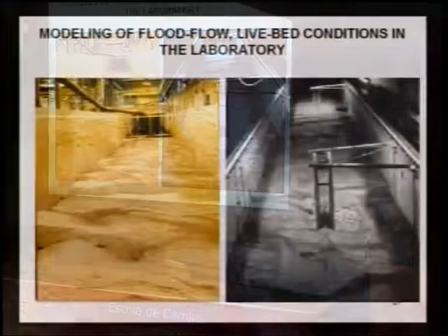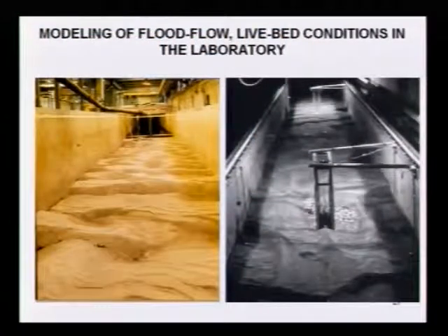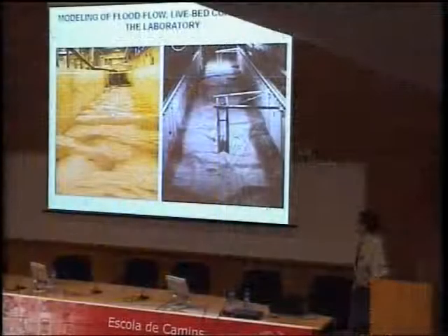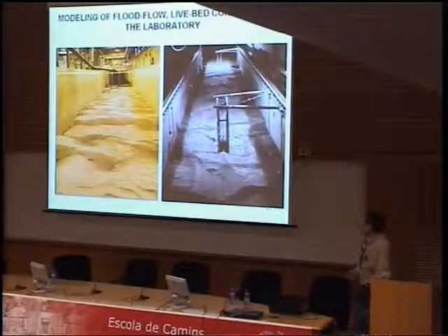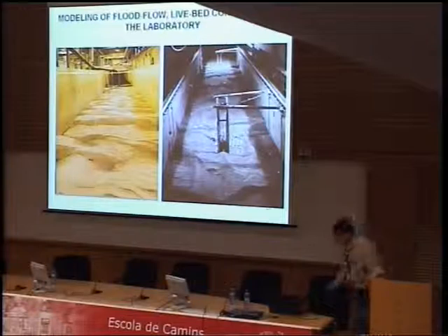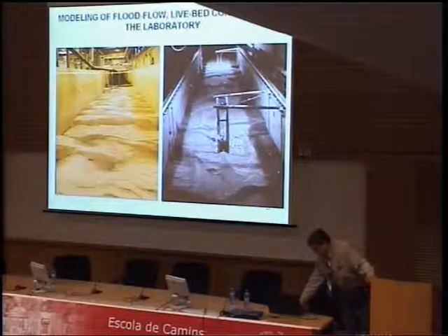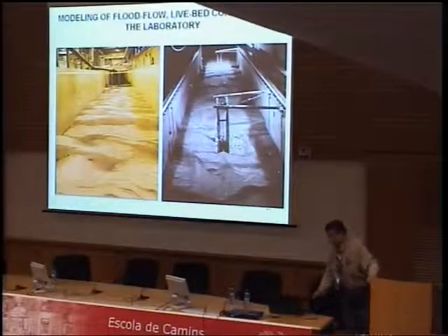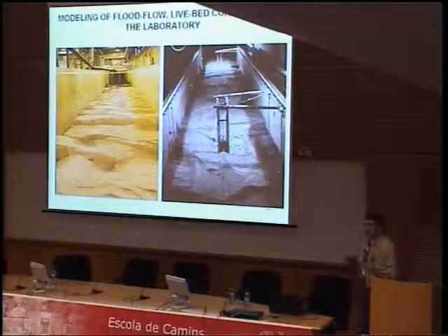Now, quite a few years ago, we did a study in which we specifically tried to look at the conditions that correspond to what a river like the Mississippi would do in a flood like a Bankfull flow. And this shows the channel we used. It's about 9 meters wide. We could recirculate the sediment, which is about 0.5, 0.6 millimeter sand. And we could place a circular bridge pier and a rectangular bridge pier in them, and we purposely made them of clear plastic so we could film the flow event looking upstream from inside the pier.